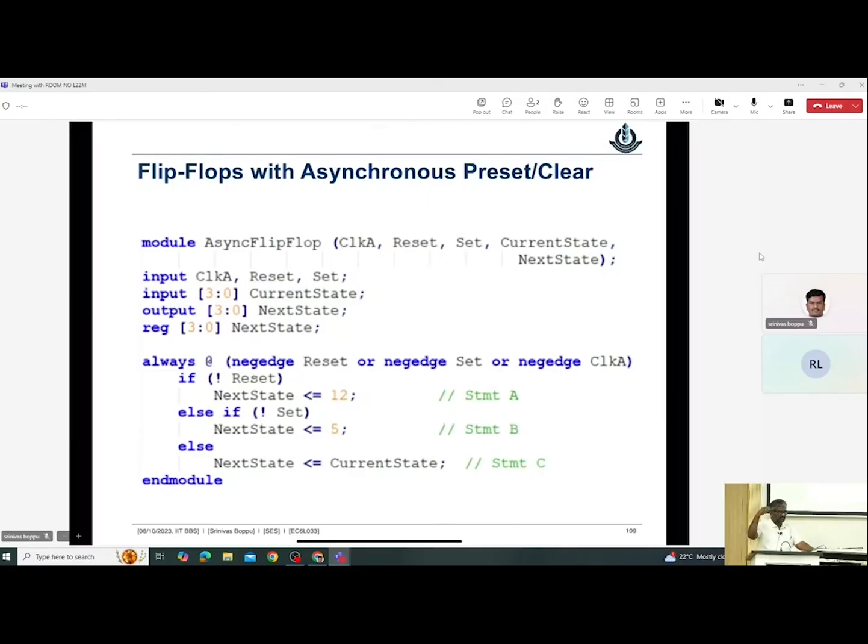Earlier what we said, maybe I can repeat, was that when we are synthesizing with the latches, we can have a latch with preset and clear pins. So we can redirect the logic, but we have only the CDN pin. Then we have to appropriately redirect the logic to the D input, and in both cases we have to make the latch open. Here let's assume that we have flip flops with this preset and clear pins. So again what we need to do is redirect this logic appropriately.